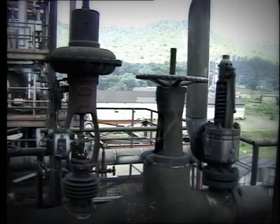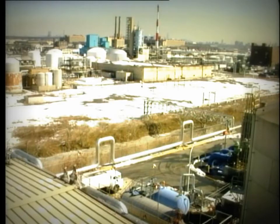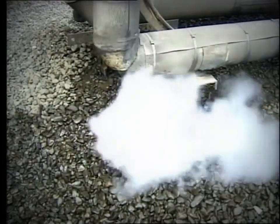Where reducing stations are installed, it is important that one or more safety valves be located downstream to protect the low-pressure pipework in the event that the pressure-reducing valve fails and exposes this piping to the high-pressure steam directly. In some cases, the auxiliary steam piping has to travel considerable distances, for example, to an oil tank farm. There is a tendency for heat to be lost from the pipework, even though it is insulated, and the steam temperature rapidly falls to saturation and condensation begins. For this reason, steam traps are located frequently throughout the auxiliary steam system.